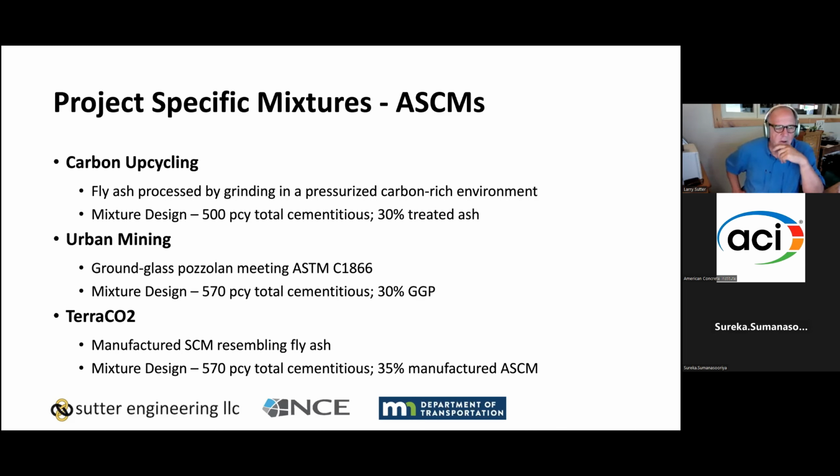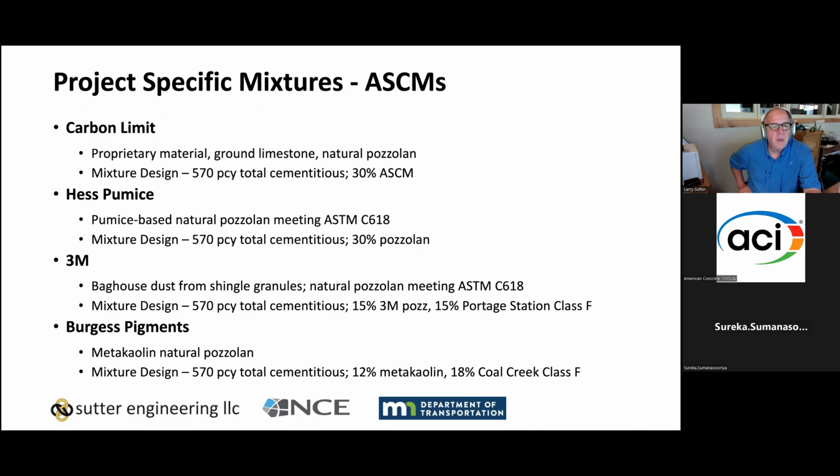Terra CO2, and again, I'll talk about these manufactured SCMs in a little more detail in a moment. Terra CO2 is a manufactured SCM, kind of an artificial fly ash, and they came in at 570 total cementitious, but they went to 35% on the SCM replacement. Carbon Limit, another SCM, 570 and 30 was their mix design. Their material is a proprietary material including ground limestone and a natural pozzolan. S pumice is just a straight pumice-based natural pozzolan, meeting ASTM C618, and they went with the standard 570 mix with a 30% replacement.